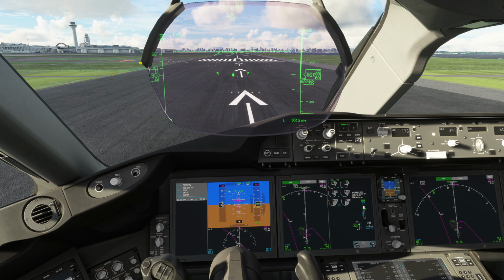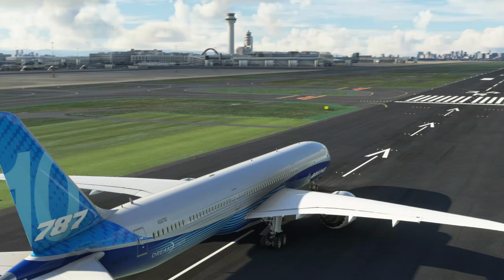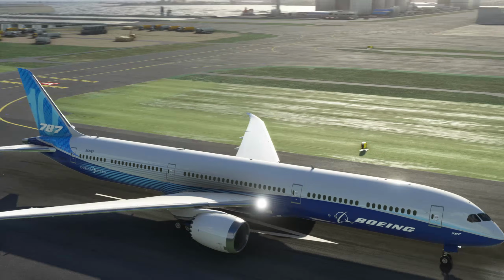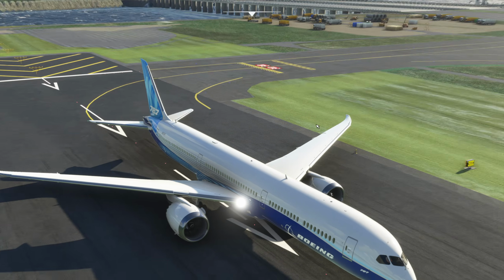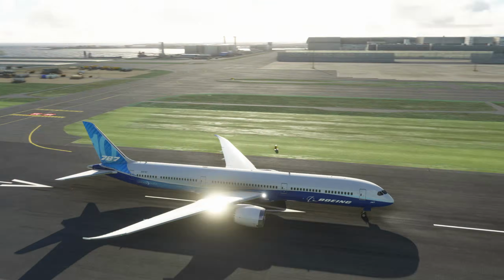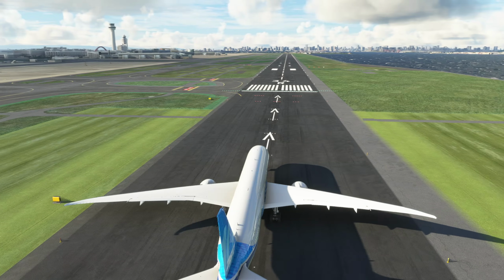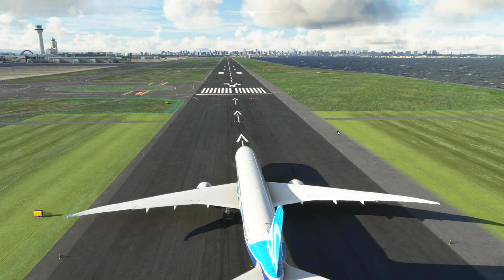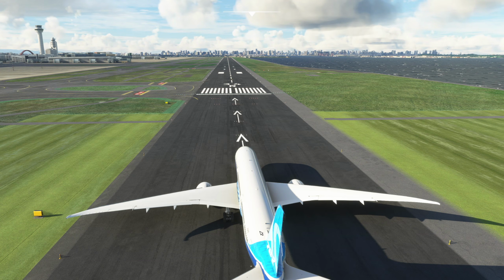Now finally, one of the weirdest phenomena I've ever seen in an airliner is something that happens on the 787. It didn't seem to happen on the Airbus at all, so I'm not sure why, but there is a big difference, and that is that, as I said just then, the airplane will try and weathercock to the right. The wind is coming from the right. You can see the white caps on the sea over there. And that's hitting this tail from this direction, pushing the tail this way, pushing the nose into wind.